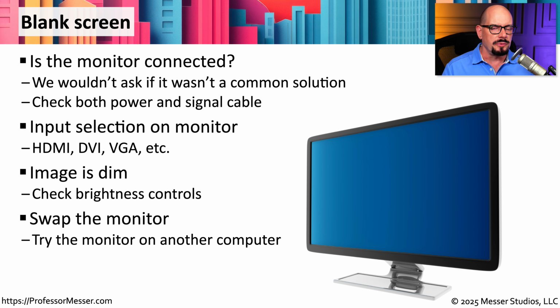If you've done this troubleshooting and you still aren't able to get anything on the screen, you may be thinking that the monitor itself could be bad. One way to check that would be obviously to swap this monitor out for one that is a known good monitor and see if you're able to see any information on the display. If you're still seeing a black screen, then your problem is probably not with the monitor hardware.